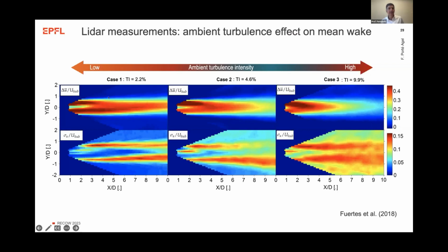But it's quite interesting, because in cases at night, where the boundary layer was thermally stratified and characterized by low turbulence levels, we had turbulence levels as low as 2.2%, which is extremely low. The wakes go on for very long distances, which is very important when you have a wind farm, because that means the next turbine, which may be located around 6 rotor diameters away, will be here. It is going to have much larger losses than I showed you for Horns Rev before.